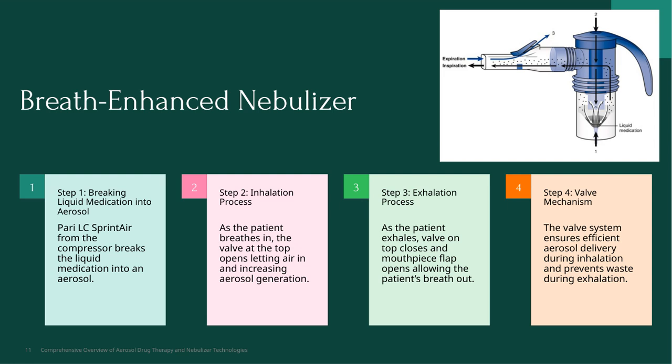during inhalation. Then, when the patient exhales, the same valve closes to prevent the aerosol from escaping, while a flap on the mouthpiece opens to let the breath out comfortably. This coordinated movement ensures that the inhaled medication isn't wasted during exhalation. Finally, the valve mechanism is critical because it manages this process seamlessly. It guarantees that the medication is delivered effectively during inhalation and prevents any loss during exhalation, optimizing the therapy and reducing waste. Overall, this design enhances the efficiency of aerosol delivery, making the treatment more effective and comfortable for the